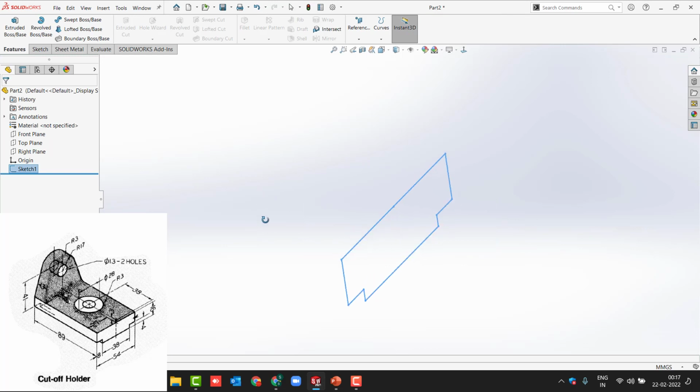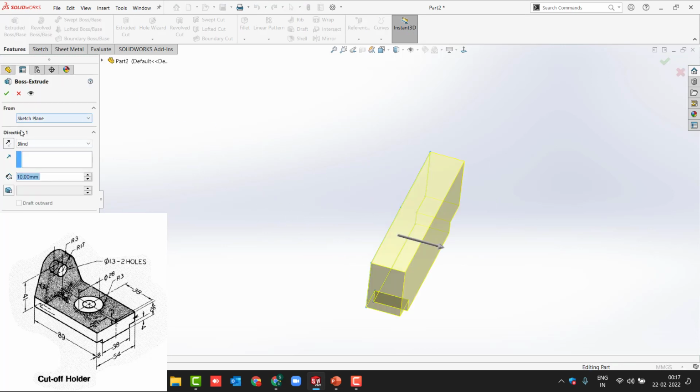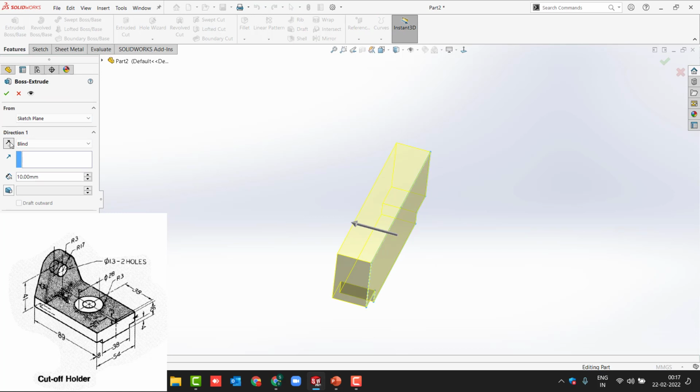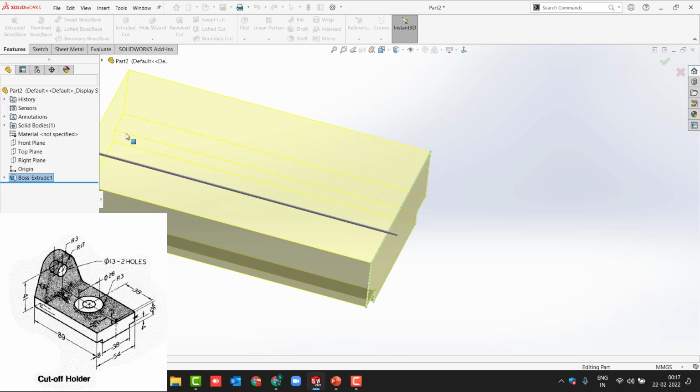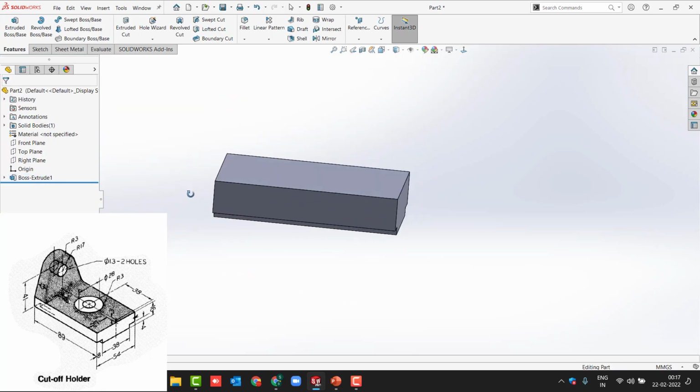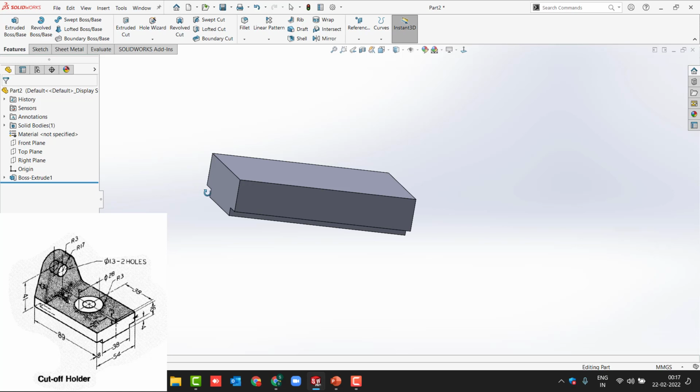Okay, so I just need to extrude it accordingly. You can use the features, reverse the direction up to 89. Length you can define it here, 89, blind, green check. Okay, and then I need to create the feature on this face.